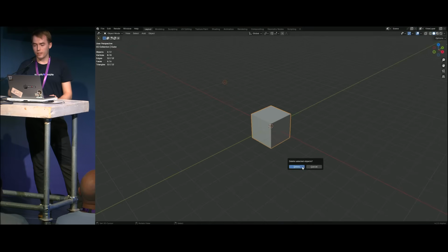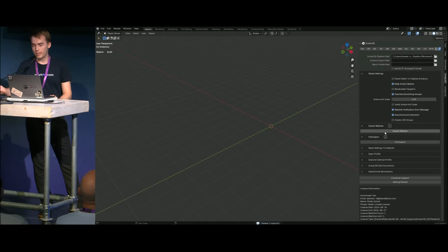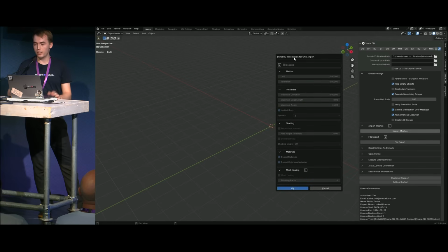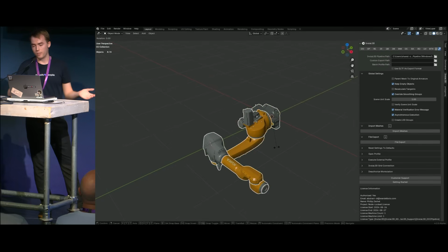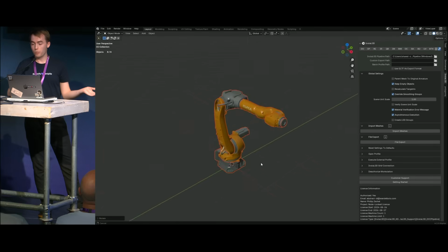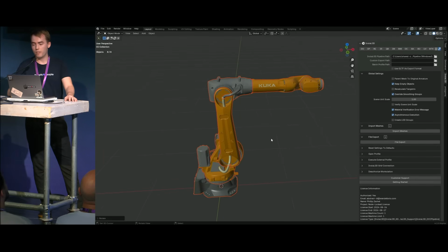Now we have our CAD data, the cleanup is done, and we face the next step, importing into Blender. This is not as straightforward as you might think. Tessellation in CAD can be tedious, and important data like hierarchy often gets lost in the process. One of the reasons we use Blender is its very extensive add-on ecosystem. For this stage, we rely on the Instalot add-on. This allows us to bring our clean STEP files in quite efficiently. No need to know the ins and outs of the tessellation settings of each CAD file like Rhino or SolidWorks, just one click and it's in.